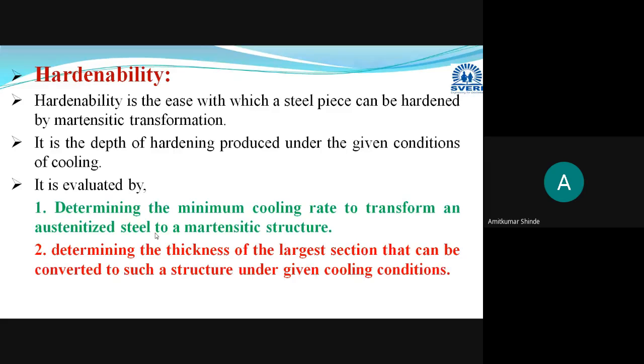And you have to determine here the thickness. How much thickness, that is, the maximum thickness where you can get the same transformation. Determining that thickness will also help you to determine the hardenability of that steel component. These are the two methods of determining the hardenability.